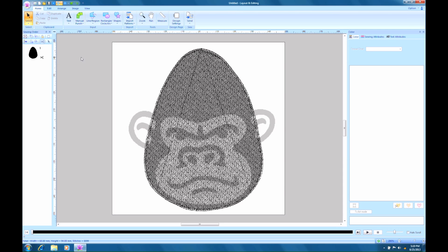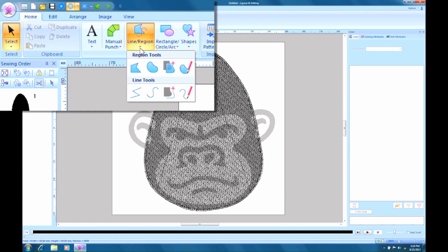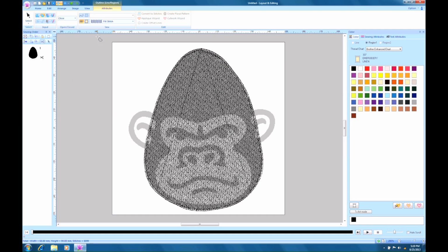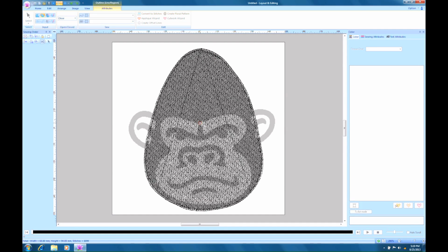Region Sewing Part 2. Face, Ears, and Nostrils. Now we'll create the parts with the next largest portion. Using the Closed Curve tool again, create a curve along the outline in the same way you did for the head.